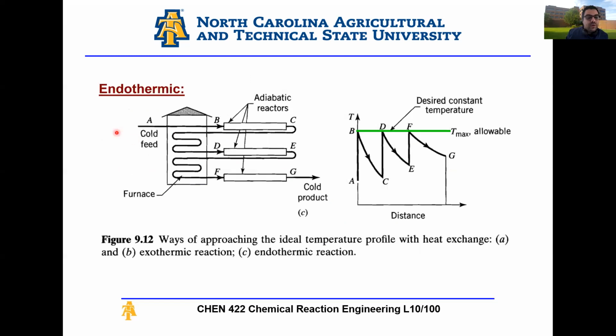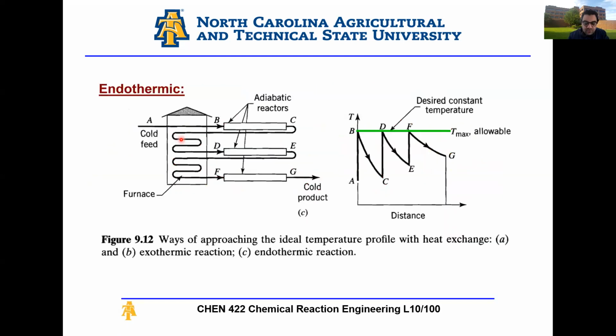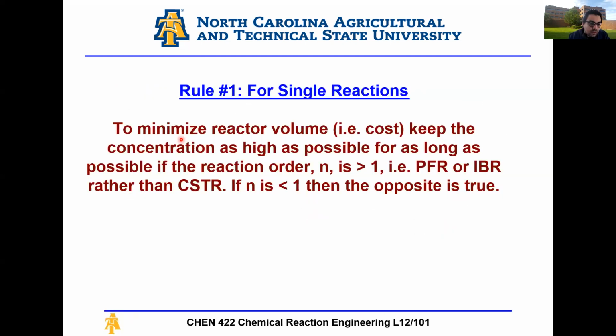Similarly, for endothermic reactions, we have a similar idea. We use a furnace to heat up your feed to the temperature you want before the reaction. And these are different configurations. And then last week, we talked about the rules for reactions: minimize the reactor volume, keep the concentration as high as possible for as long as possible.